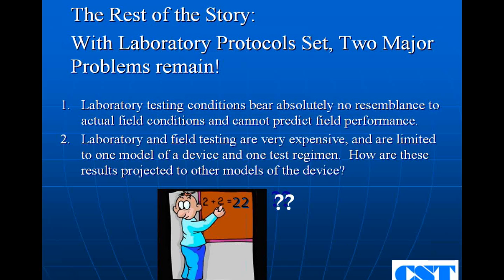Lacking anything else, I'm not being critical at all of those jurisdictions who only look at laboratory testing, because otherwise you've got no standard. But you should keep it in the back of your mind that laboratory testing with pure silica sand material at a certain size may or may not have much to do with how a device would actually work in the field.